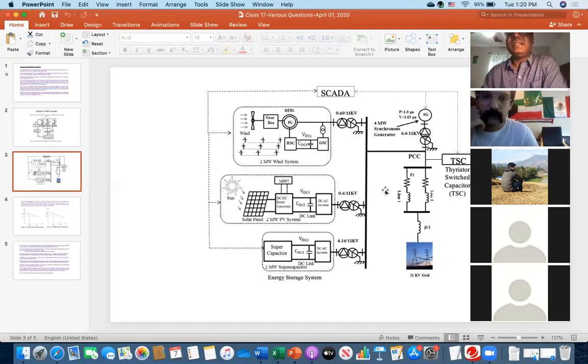So therefore, in this case, because all voltages appear here, you can collect the voltage signal. This means you can say, I will collect the total voltage information, and that signal will go to SCADA. Everybody keep in mind, in the case of a microgrid, the total voltage information is the most dominating, most helpful for making a decision by the SCADA. So therefore now you got the answer.